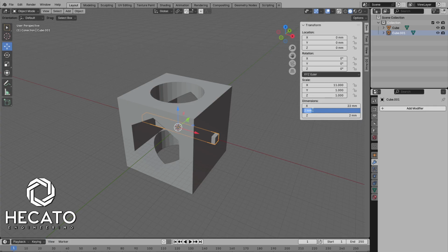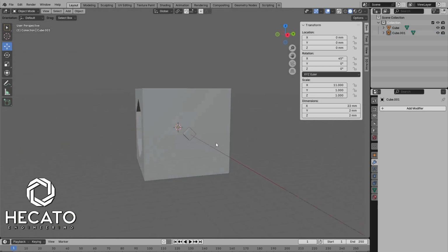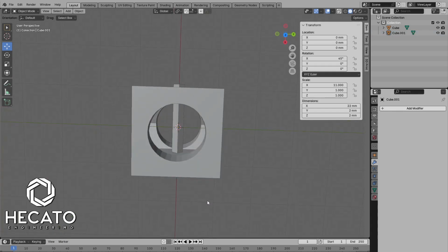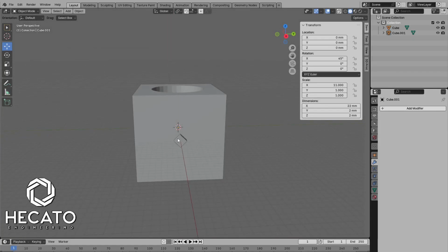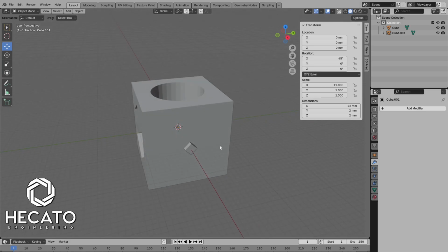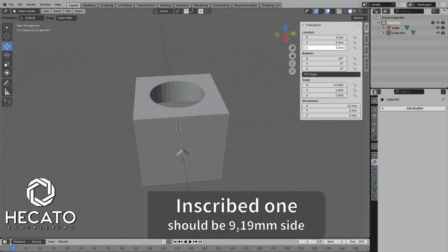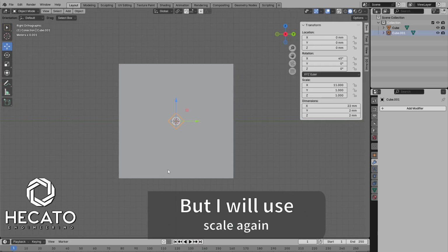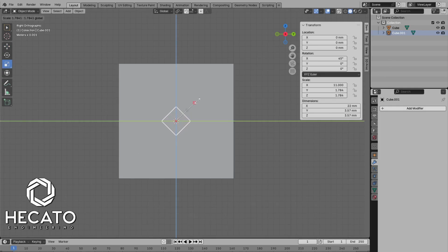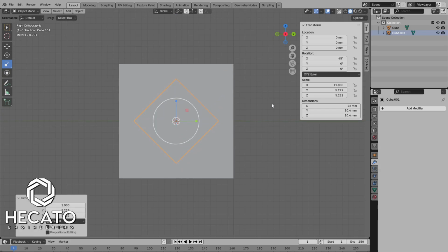Great. This is the axis that I wanted. I'm going to rotate it along the X, 35 degrees. Perfect. And I just need to scale it up so it's diagonally around 13 millimeters. We're going to choose this view, zoom a little, select the cube, scale, and zoom.